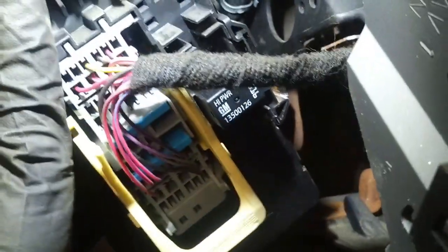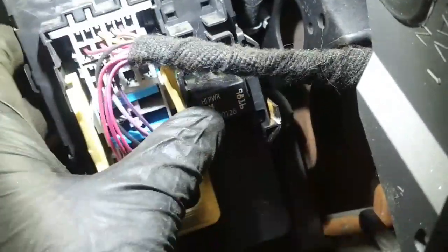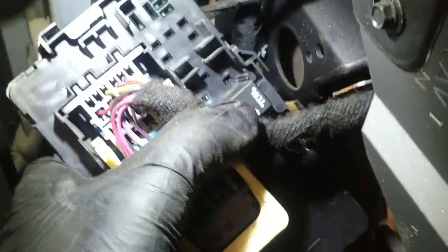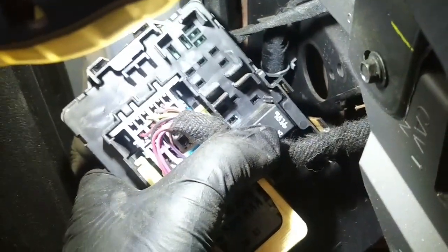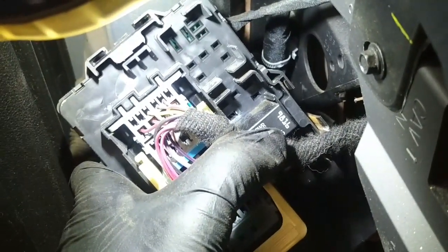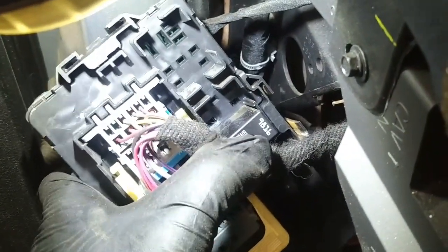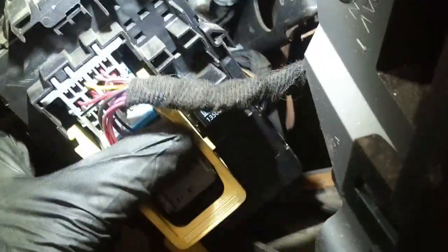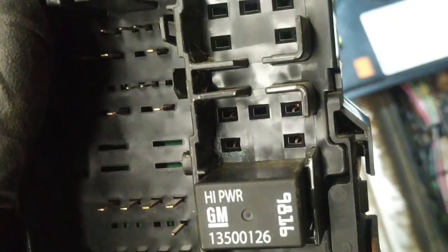But I'm going to have a look at those relay terminals. I don't know if the camera is going to see this, but if you look at pin 30 of that relay, which is just below the wiring harness here, you can see some slight green corrosion in there. Now, why there would be some corrosion on that terminal, considering the rest of the fuse panel looks pristine, I don't know. Well, we're going to take this fuse panel out and have a look at it.